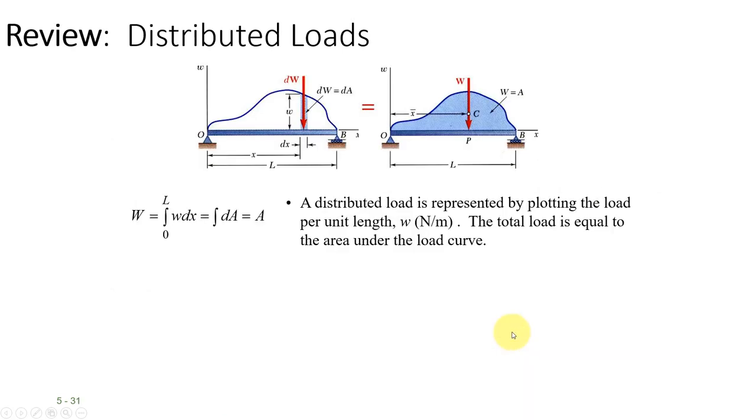And we did the same thing for distributed loads, right? If you're looking at the area under the curve and you have some kind of an equation that describes a pile of snow or something, so weight dx, you can figure out two things: the total force, if I added the entire snow pile together, and then instead of trying to keep track of every snowflake, we just say where's the center of mass, and it acts like all of the snow is acting at that one point.